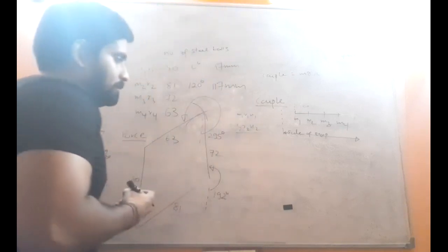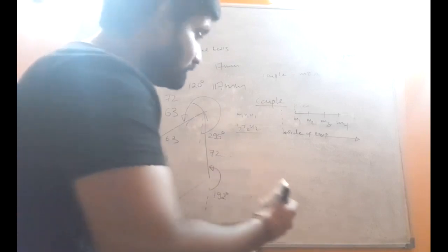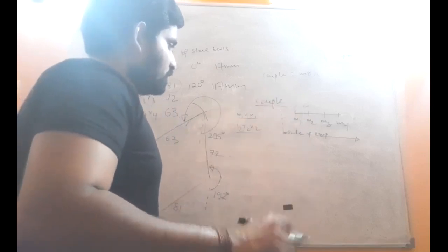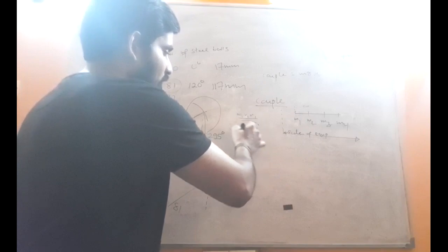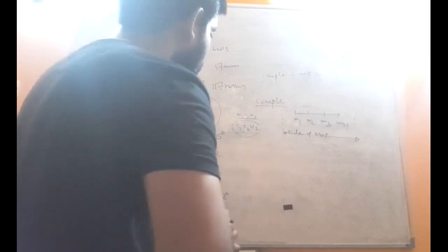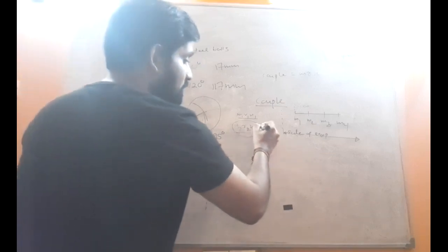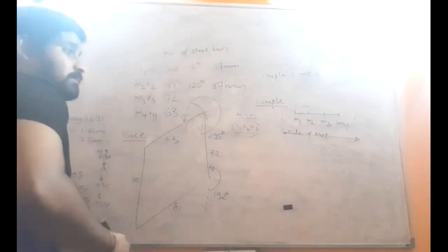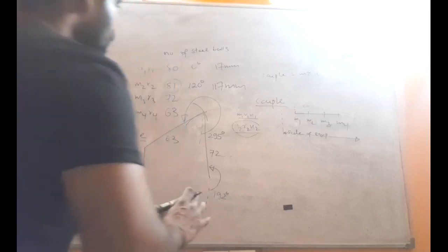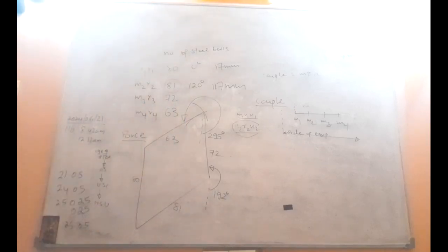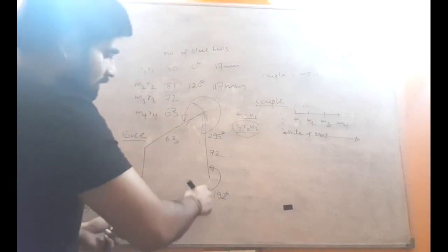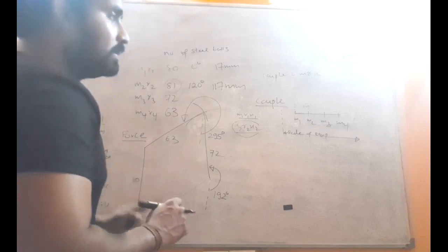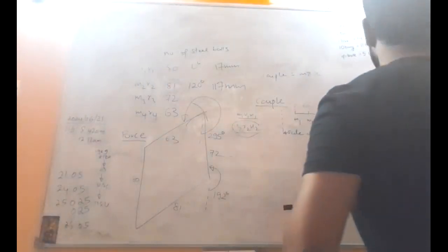Because the position of the plane of the first mass is considered as the reference, right? So then what about M2R2X2? This we know because X2 is 100 millimeters with respect to the position of the first mass, right? So now carefully focus. Now this vector represents the centrifugal force for the second mass, right?